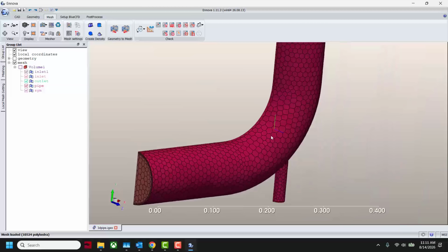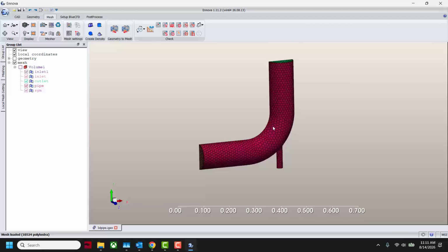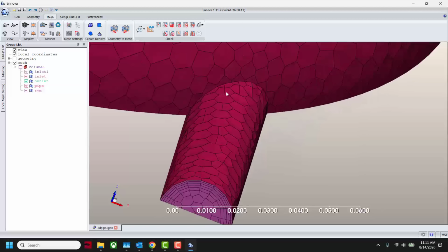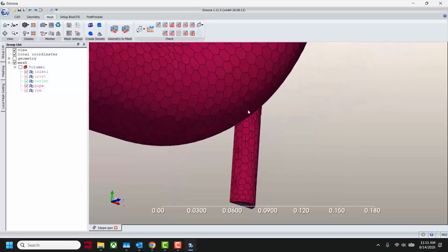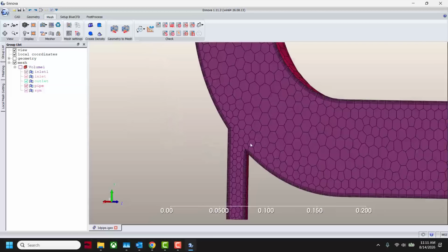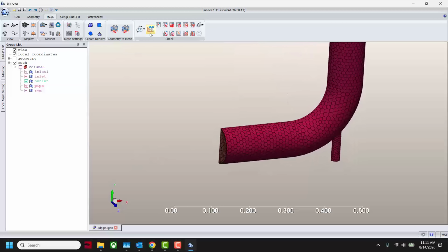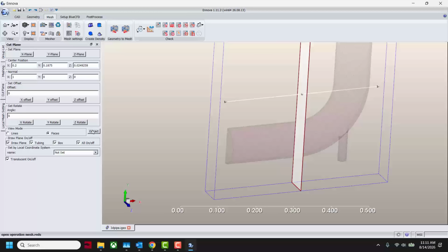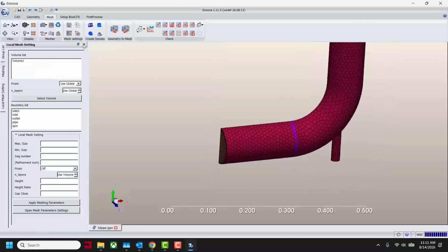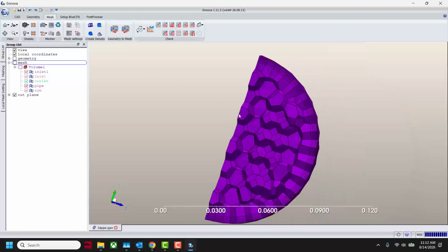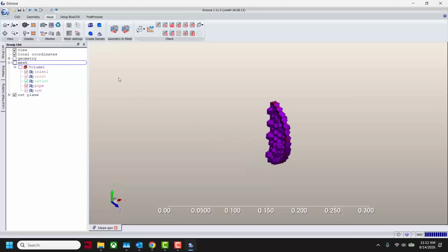And this is the difference, if you're wondering, why wouldn't I just use OpenFOAM with the open source mesher that comes with OpenFOAM. It's being able to create really high quality meshes like this that is what we bring to the table for OpenFOAM. So now if we take a little slice through it, you can see now we have filled in the volume with polyhedral elements.